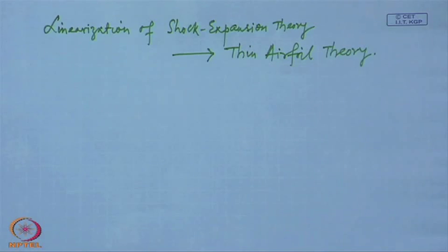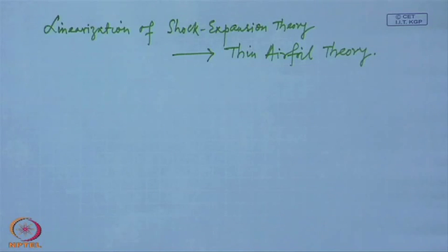As you have seen, if we apply this shock expansion theory, we get exact results. However, this shock expansion theory is not very convenient for a curved airfoil section, and that is, the shock expansion theory result cannot be expressed in a concise analytical form, and hence not suitable for various applications, particularly having curved surfaces.